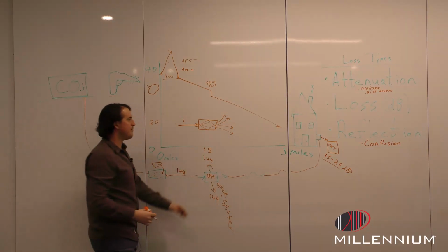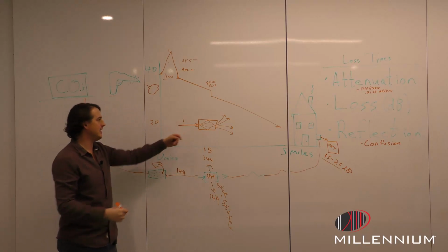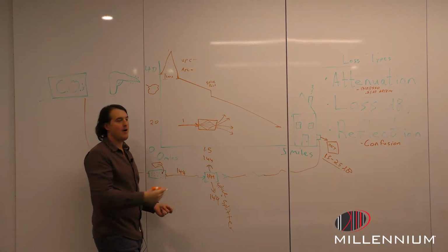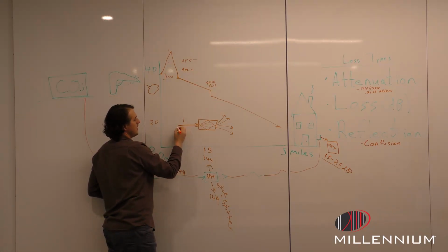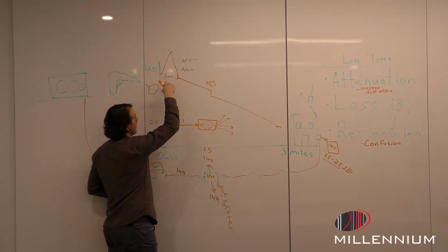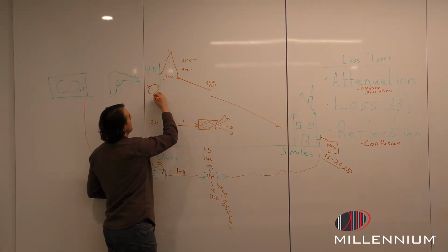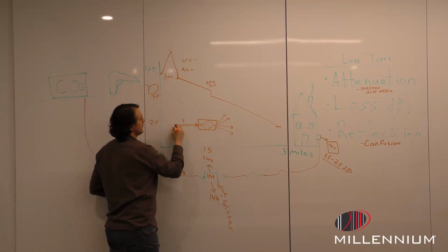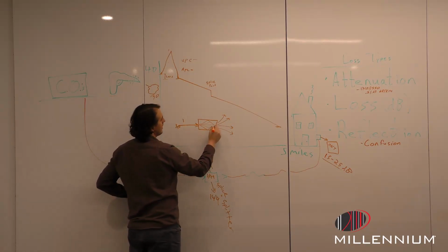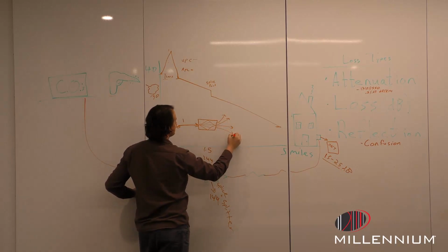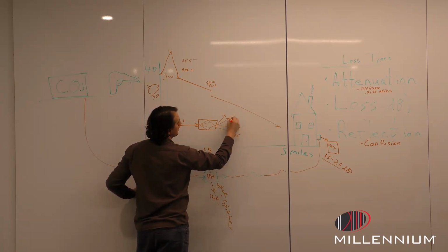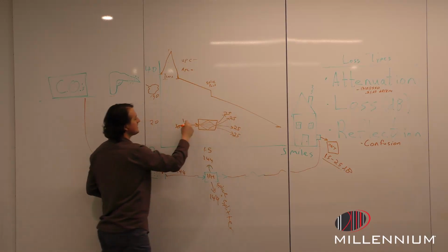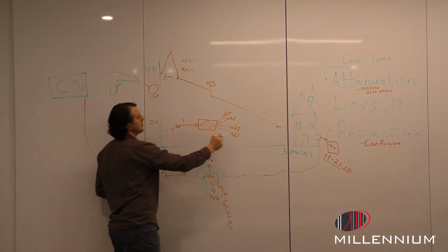Okay? So the power of the light being injected into this, we lose a lot of power. So it's a larger loss event here. Right now we're at approximately 30 dB. So if we're at 30 dB, that light's being split up, and on the output side of each one of these, it's a huge loss event. This might now drop down to 25. And the larger the split, so we got 30 coming in, 25 going out.